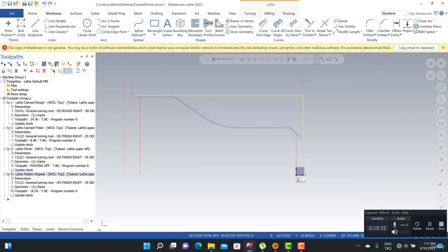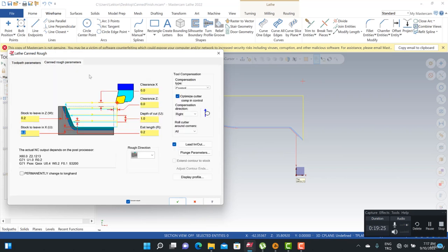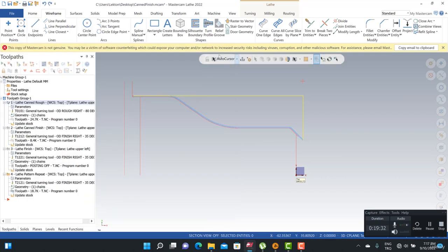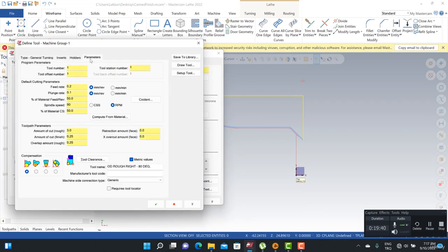Okay, this is the advanced information. You can change your radius. If you would like to change your radius for your cycling process, you need to turn to control as the tool compensation type. Of course, at that point, you can turn to your CNC and organize your tool radius, and you need to organize your compensation parameters.